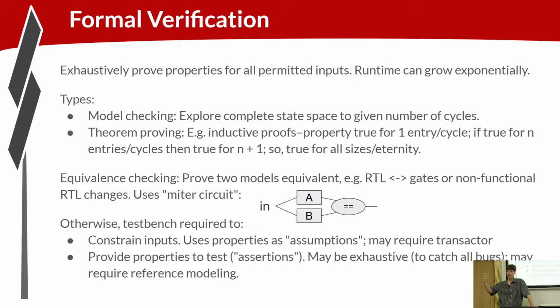One is this one-hot vector that selects something, and the other should come along 3 cycles later and align with that one way or another. You might need to define some logic at the input that's generating those, in sort of a controlled way to ensure the property that you need on the input.